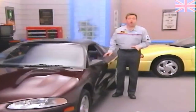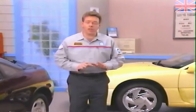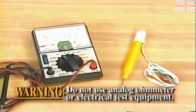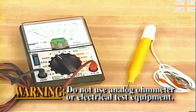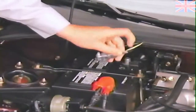In order to avoid injury to yourself or others from accidental deployment of the airbags during servicing, there are certain precautions that must be followed. When diagnosing the airbag system, use only a scan tool or a digital multimeter. Never use an analog ohm meter or electrical test equipment like a self-powered test light, because they could cause the airbags to deploy. Always disconnect the battery negative cable and isolate it before working on system components.